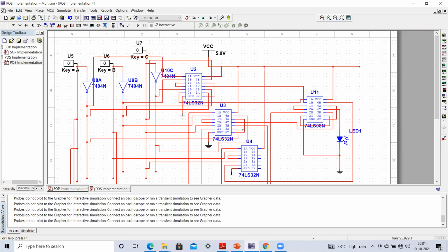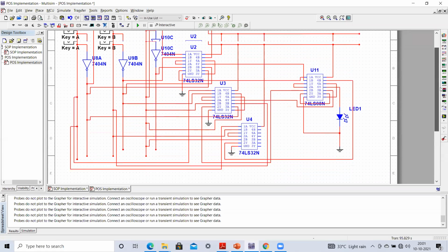Here you can just test it. I'm just checking it. Okay, it is connected with b. So it is fine. Its output is connected here, and then again the other input should be c. This should be connected to c. Here it is connected with c bar. I'm just making a reconnection, deleting this connection, and then making this connection with c. So hopefully, if these are proper connections, then we should be able to verify all the combinations.